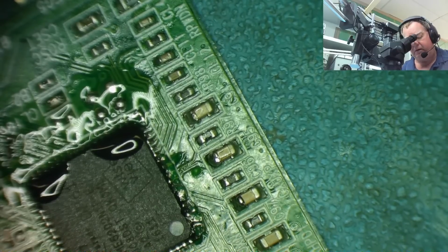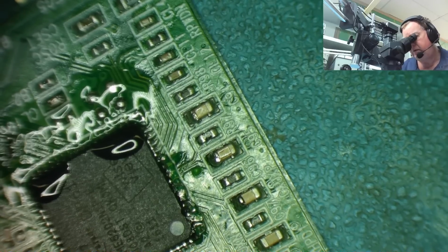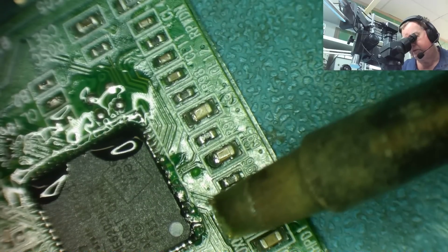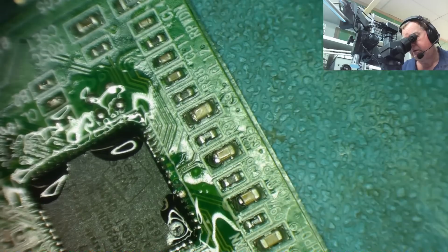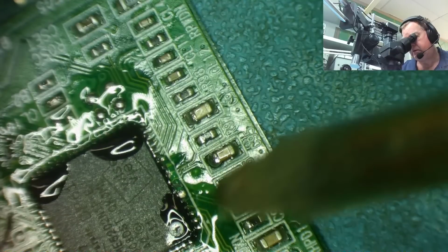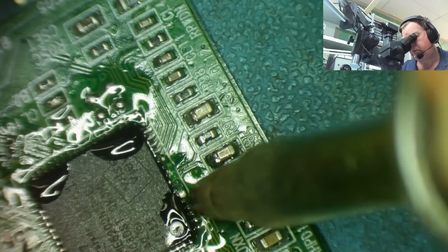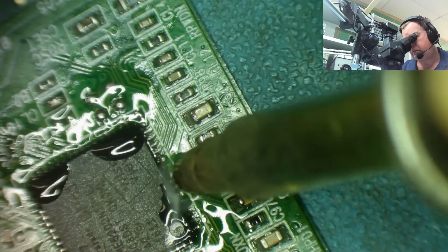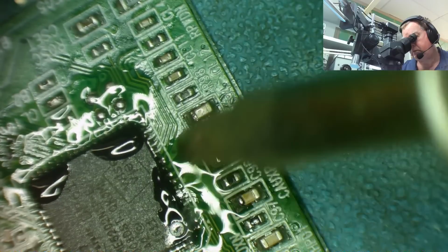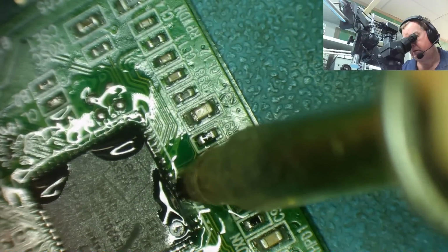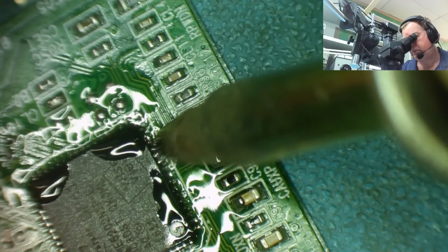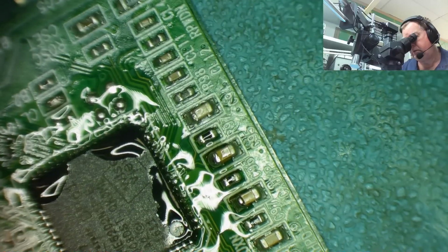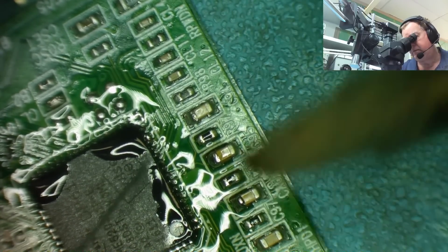For this I'll probably just need a little bit of the 0.2mm solder, nice thin stuff. And let's just see. I want to come in this way up because I don't want to disturb any of these capacitors and resistors here. If I can't, I'll have to come in flat. I think there's one just here maybe. Okay. I think I've still got ones at the end. I mean those are solder bridges there.